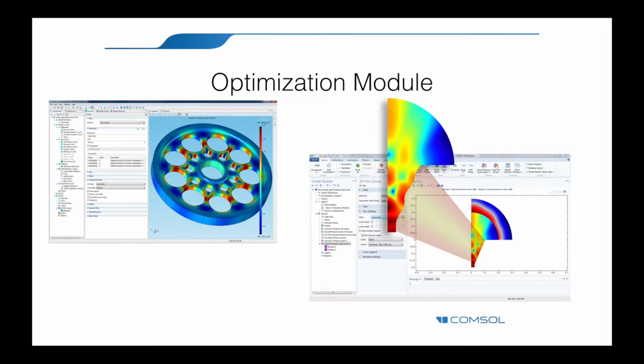Built-in algorithms handle the problem of performing optimal adjustment of the selected control variables during an optimization study. A number of different strategies are currently implemented in COMSOL Multiphysics. Since we are doing a shape optimization, modifying the geometry, we use a so-called gradient-free optimization algorithm.